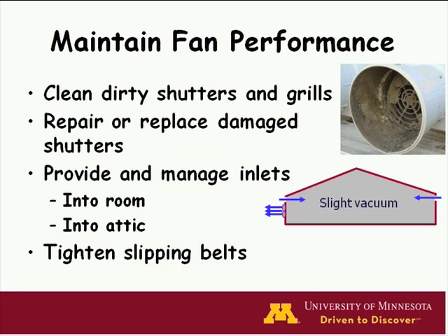Fan performance can easily be reduced by 40 to 60% if they're not well maintained. In these conditions, you've got the fan running, and it's using electricity, but the airflow rate is just a fraction of what you'd expect. And you end up running more fans than you need to.